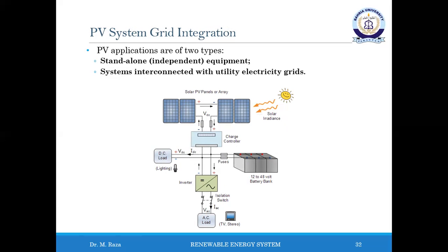Batteries are often used in PV systems for storing energy produced by the PV arrays during daytime and supplying it to electrical loads as needed. Moreover, batteries are also needed in tracker systems to operate at MPP in order to provide electrical loads with stable voltage. Nearly most of the batteries used in PV systems are deep cycle lead acid batteries.